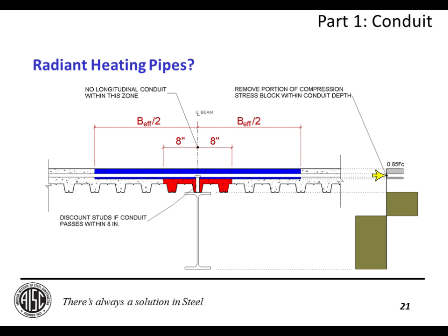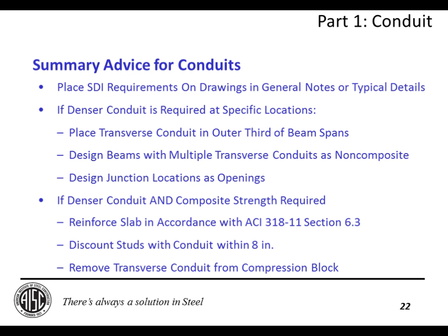So again, this is a lot of extra work to take all this into account, but if you do need to have a large amount of conduit in your slab, it is an option that is feasible for you to implement. So summary advice for conduits. I would place the SDI requirements for minimum spacing, maximum sizes, etc. directly on your drawings as a baseline.